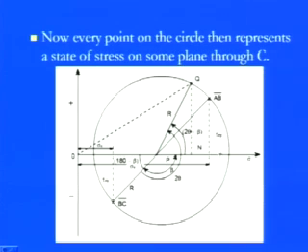This is pretty easy. Or vice versa, you have sigma x, sigma y and tau xy. It's pretty easy, because once you know sigma x, straightaway from the origin draw sigma x and make the vertical projection until it meets a point. Make those points, this is the one point. Take another point, sigma y, on the x axis, this is my sigma y, and then take tau xy. So you have one point from sigma x and tau xy, and another point from sigma y and tau xy. Now make this diameter, and once you have the whole diameter, take the center point on the x axis and draw the circle. Once you draw the circle, you have all the information required.